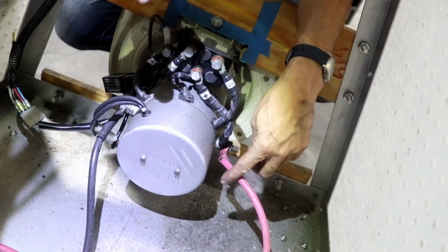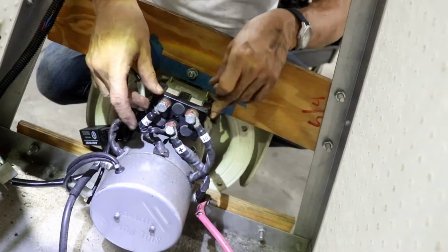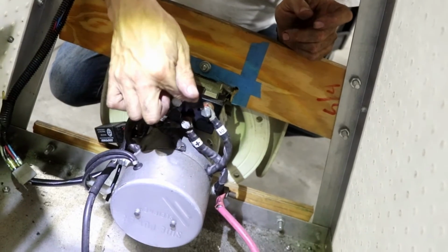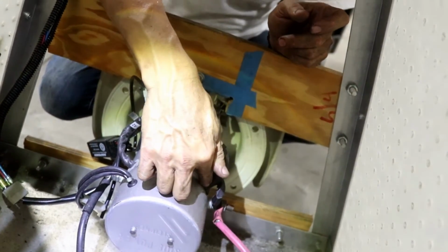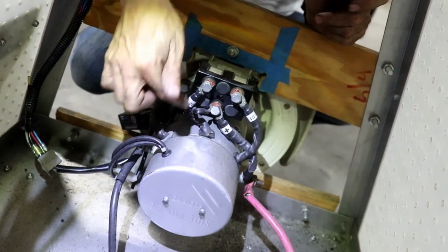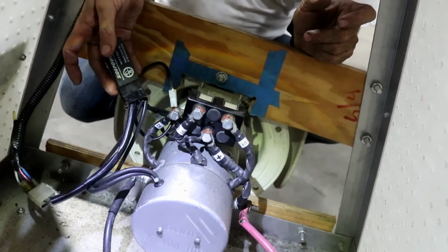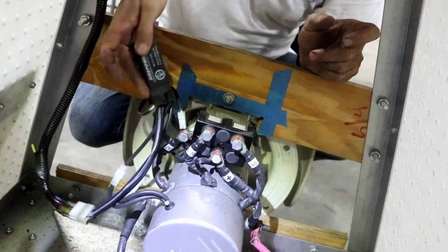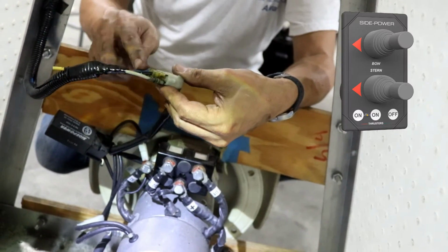The positive enters here and goes in the middle of the solenoid control box, and depending on the signal entering the solenoid control box, the current goes here for clockwise rotation or goes here for counterclockwise. The signal goes for one direction or the other, coming from this relay. This is the typical relay, and this relay receives the signal from the joystick.